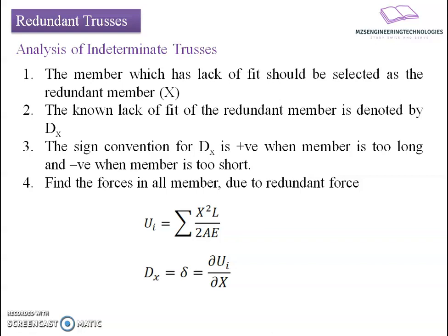We were discussing the effect of lack of fit in statically admissible trusses, and statically inadmissible trusses, meaning indeterminate trusses. In the last lecture we dealt with statically admissible frames, and we came to the conclusion that the lack of fit will cause deformation of the member, but it will not develop any stress component in case of statically admissible frames.